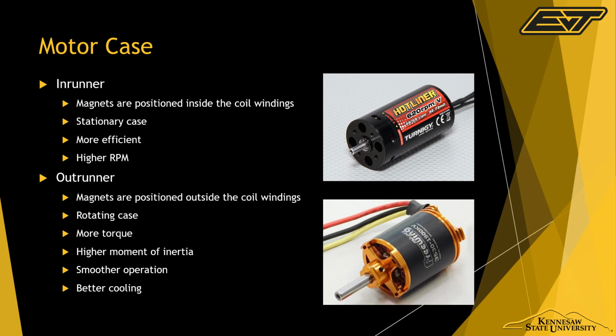Trust me, you don't want to use a gearbox. First off, it's going to lower our efficiency a lot more than the efficiency that we would gain from using a higher RPM motor. And there's more mechanical parts, so there's more points of failure. So that's why we really need to find a motor that's within the RPM of sprockets that we can use. Now, those sprockets are based on the tire diameter, because you obviously can't have a sprocket bigger than the tire diameter, and the minimum diameter of a sprocket that we can put on the shaft of the motor depends on our chain size, actually.